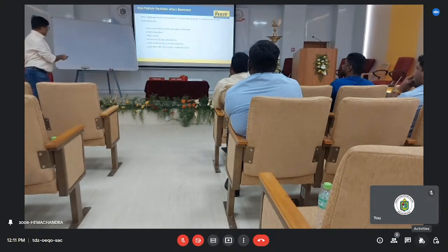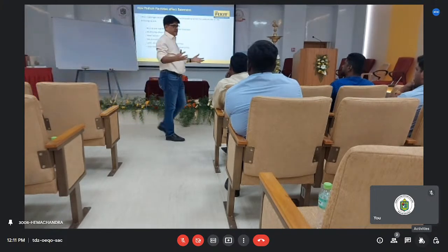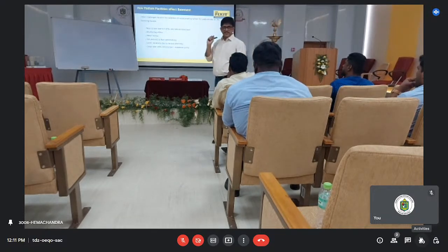And then, of course, this is a critical issue: it is a large span. And a large span will have movement to it. There will be a lot of expansion joints and construction joints already in the structure on my top slab, which are all potential threats to my structure.